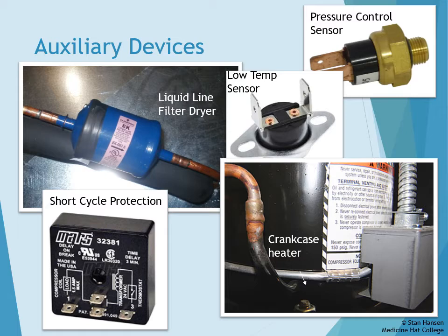And lastly, we have the crankcase heater, which is only found in some systems. Its job is to keep the compressor crankcase heated so the refrigerant will stay a vapor, and it keeps the refrigerant out of the oil.